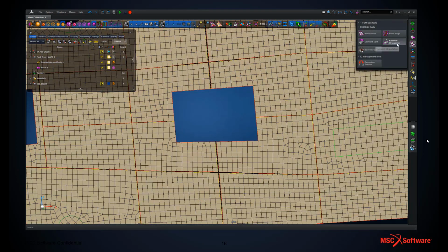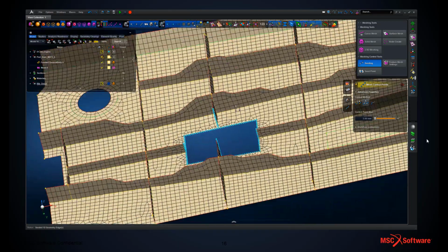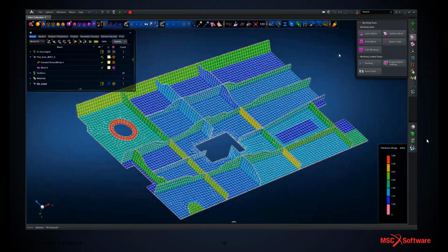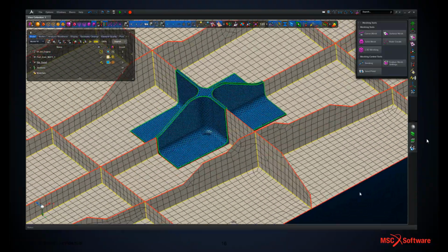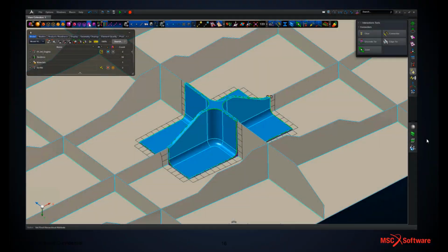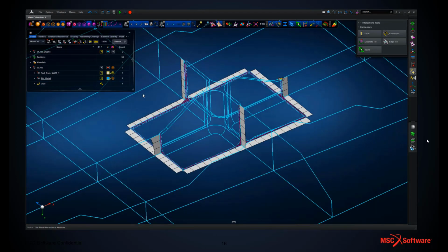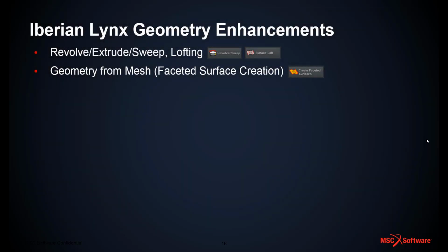We've remeshed the structure using a new element edge length, and we've got full control now with this faceted surface geometry if we wanted to generate further modifications, so we could seed that surface if necessary. Key here is the faceted surfaces remembered the underlying shell thicknesses, so we don't need to repropertize. That's taken care of. So we dropped in a portion of 3D mesh geometry. We can glue those components together using the standard glue connector technology, and then run the model. So a very quick way to work with orphan bulk data file definition, and to modify that to modify or introduce new geometry as required.